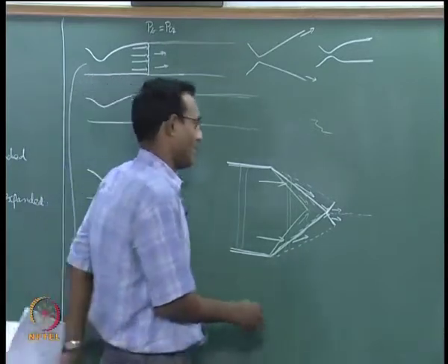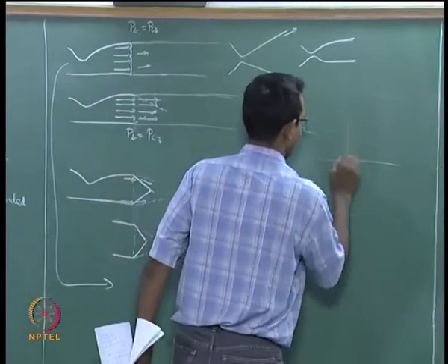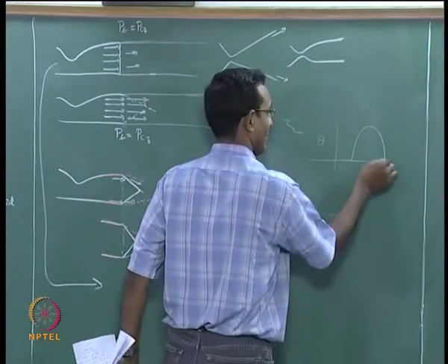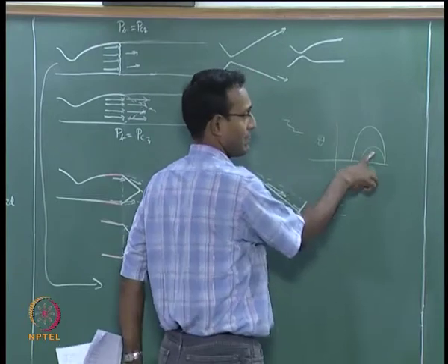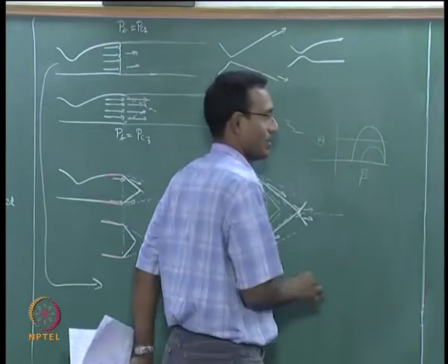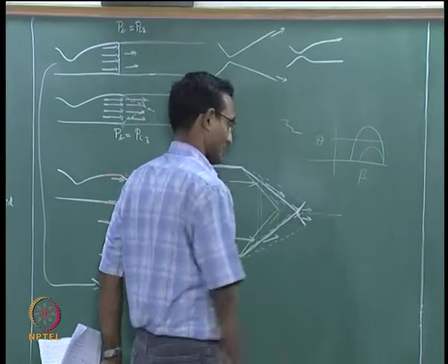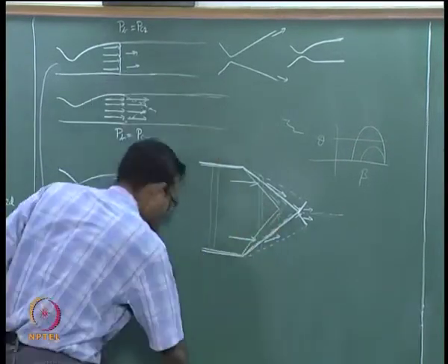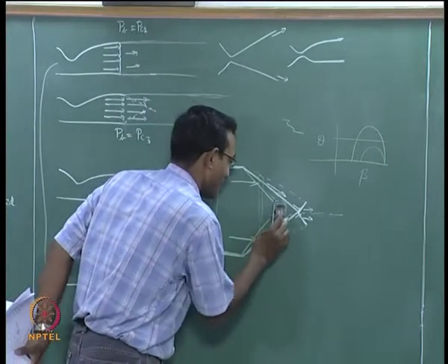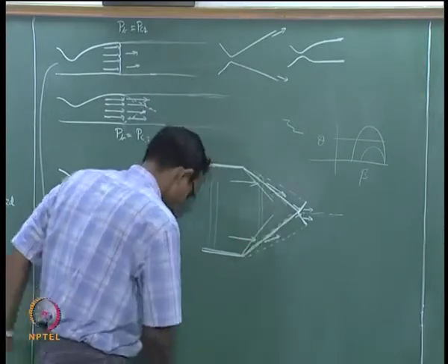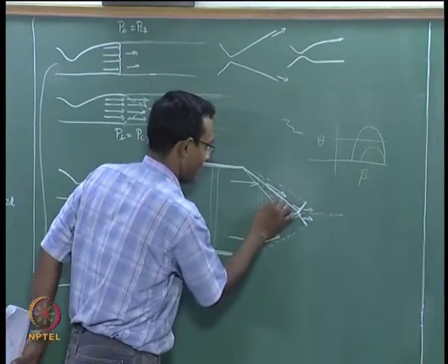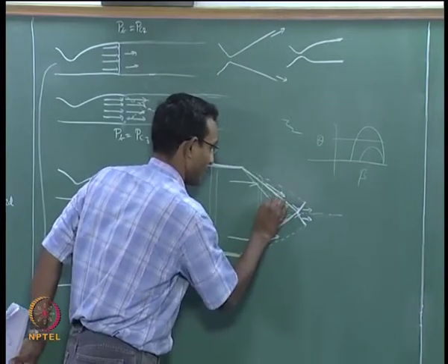What happens at that point? We will go cross that theta-beta-M curve. Okay. If it is a weaker Mach number and I want this strong thing to happen, it has crossed. So, what happens in that situation? It becomes a Mach reflection. That is what I want you to think about now. Since I have introduced you to the other simple thing, now you can think about a Mach reflection. Along this dotted line, there is going to be this Mach reflection happening out there.